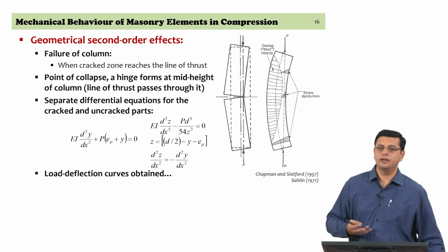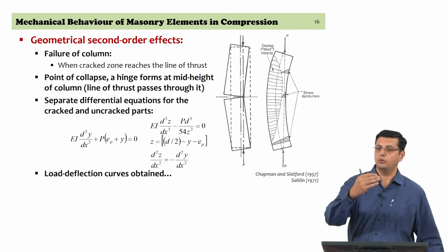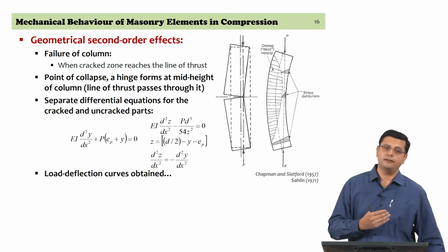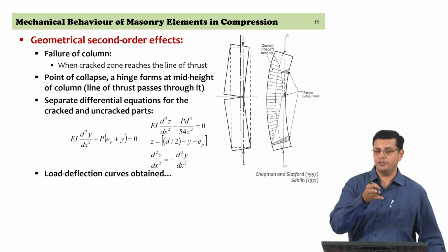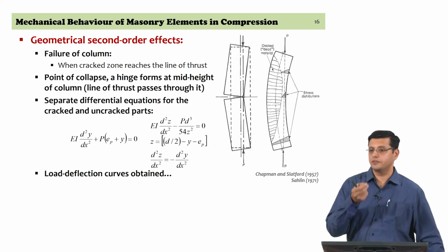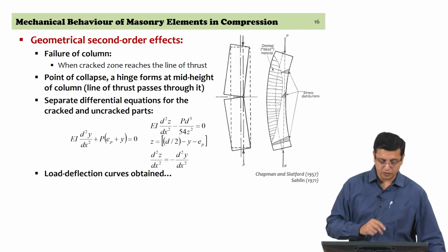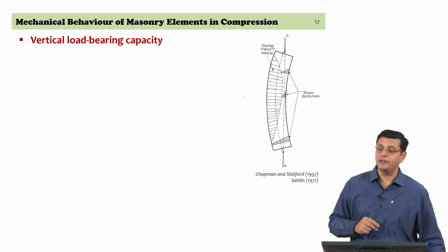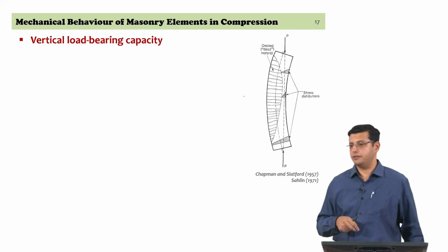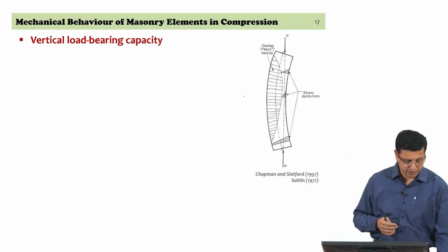And these load deflection curves will actually be able to tell you how much the strength in compression of the element is going to be different from the compressive strength of the material itself. So, let us examine this. We want to calculate the vertical load bearing capacity of the wall, and these are the assumptions that we begin